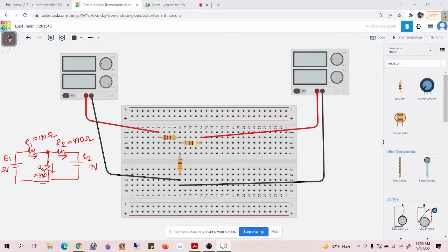We can measure it with an ammeter, but honestly, using ammeters would make your circuits a bit clumsy, because ammeters always need to be placed in series with a component. That is, if you are trying to measure the current flowing through this resistance, you would have to place the ammeter in series with the resistor. So putting ammeters in circuits becomes a bit clumsy when you are trying to solve all the branch currents. So I won't be directly solving I here.